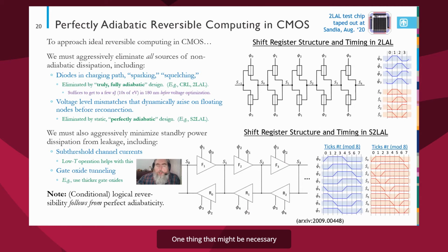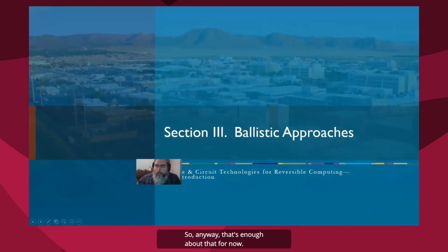One thing that might be necessary for realizing that prediction is aggressively minimizing leakage power through reduction of subthreshold currents by operating at low temperature, and optimizing the device structure to also reduce gate leakage currents. So anyway, that's enough about that for now.